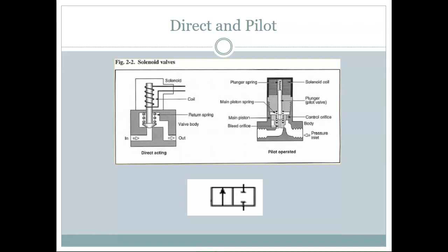You can use them with air, but how do they work? What causes them to trigger? Pressure. What kind of pressure? Well, excessive pressure on your system. You generally got a way to set this. So let's say my system's normal pressure runs between 60 psi and 70 psi.